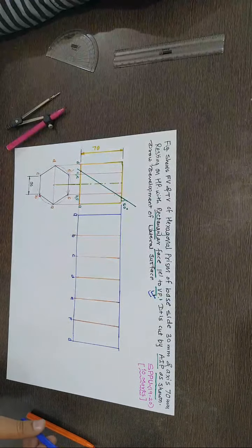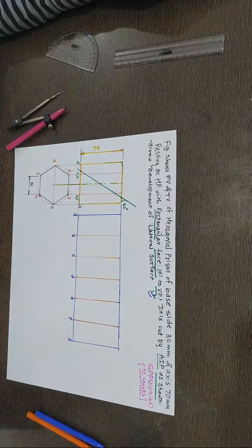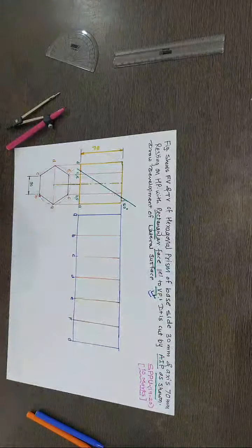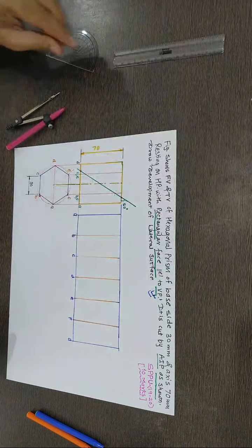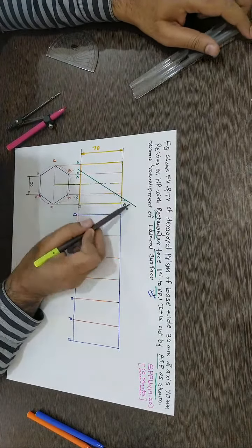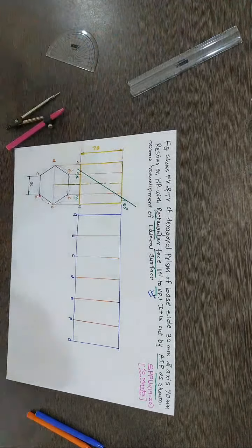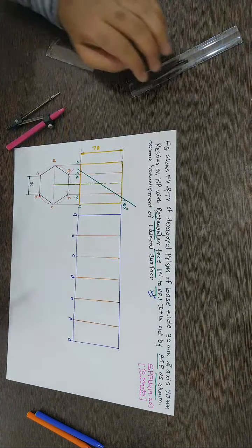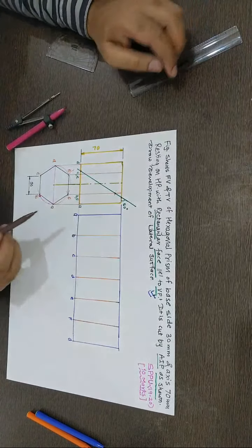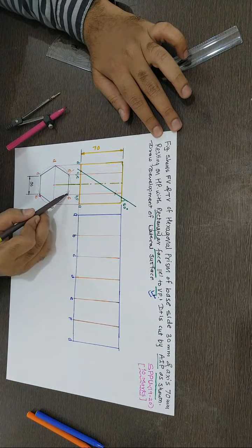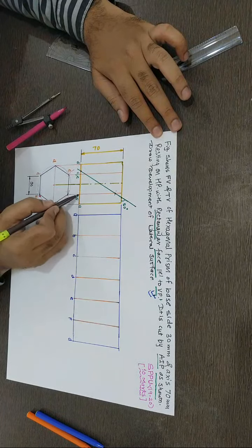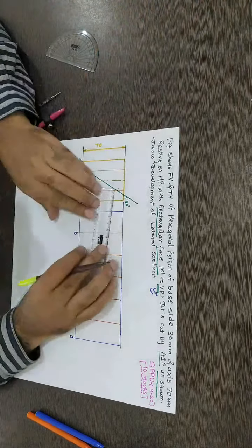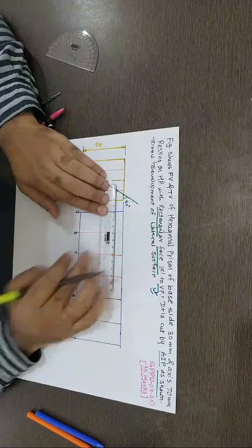Now, first, a very simple, conventional way, you just project the points as in previous cases. This plane has an intersection with this prism. So this first point is for which edge? It is F, as well as this one is on B. So you can see this is B and F. So extend those points up to the corresponding locations here in the development.